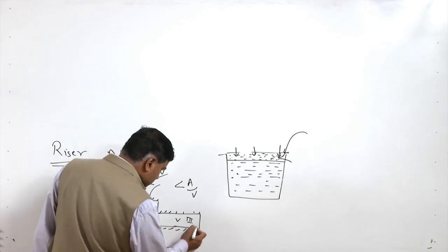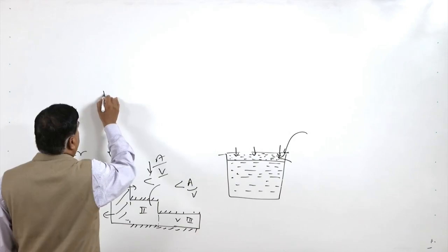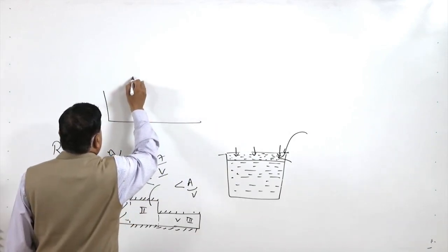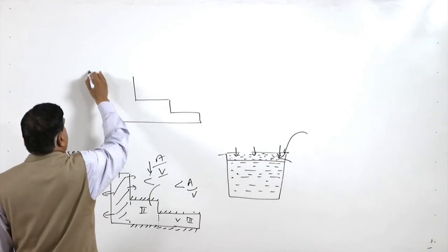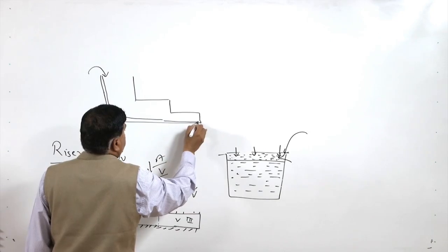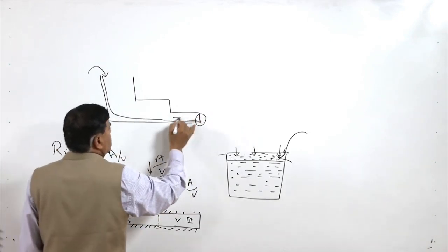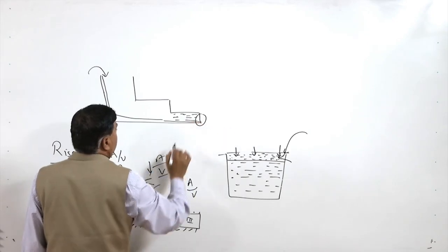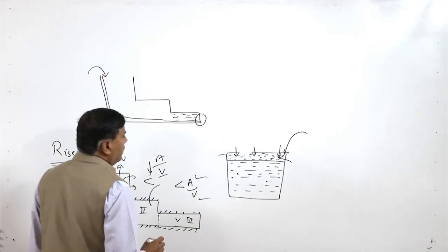So, in this case we are feeding the molten metal in this mold, which is of this kind, where the molten metal is being fed say from the top. The molten metal will reach this zone, the remotest zone from the feeder. This zone is expected to solidify first because of the higher surface area to volume ratio.